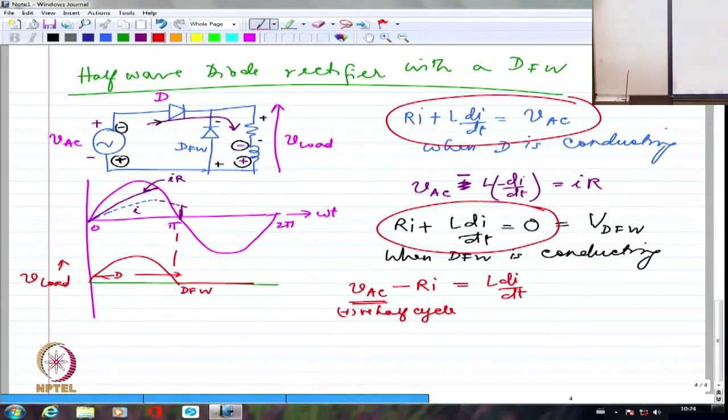But when this is reaching the negative half cycle, I am going to have VAC also of the opposite sign. So VAC will also become a drain on the inductance stored energy, because that is also very actively opposing the flow of current.